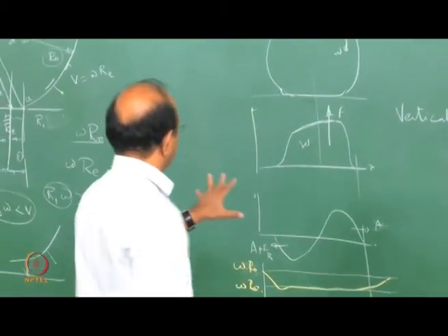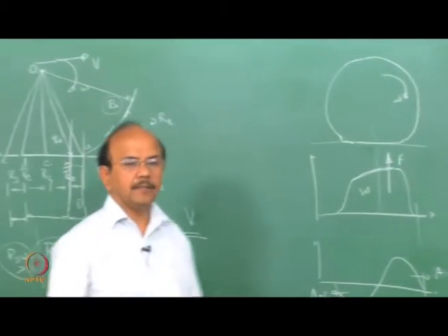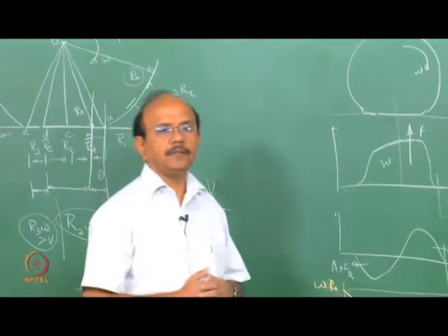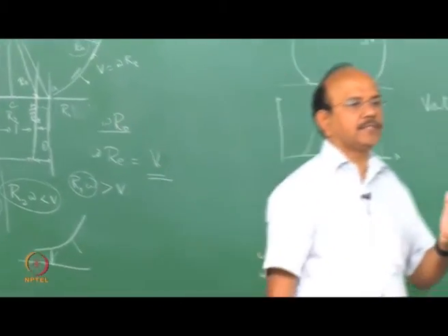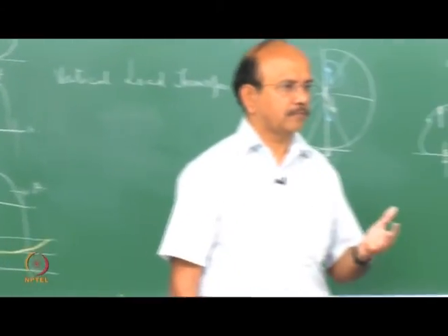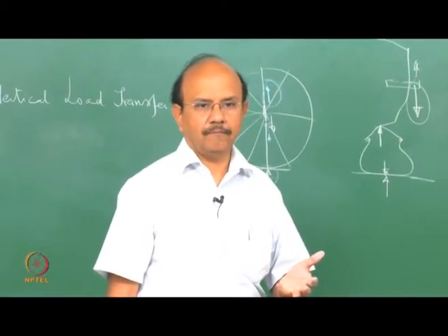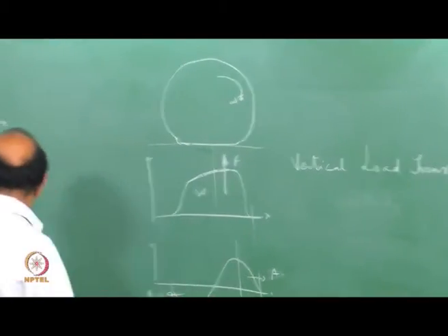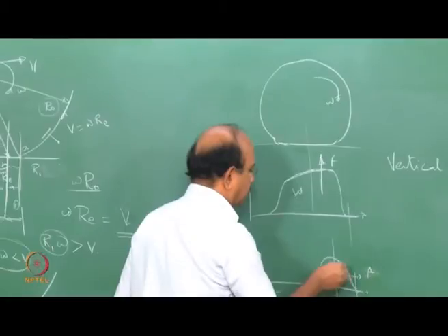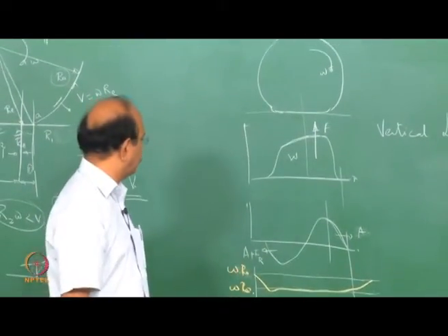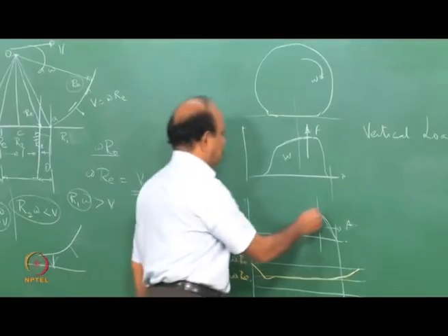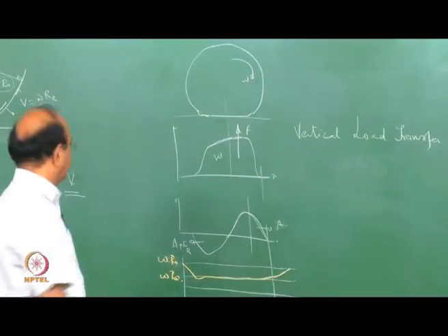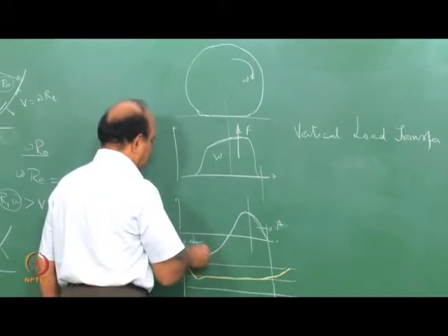Let's see what happens because of this variation in the radiuses. Obviously, this variation in radiuses causes a lateral force. The lateral force in the first part up to A goes in one direction, then starts dropping, then goes in the opposite direction, and then goes up again.